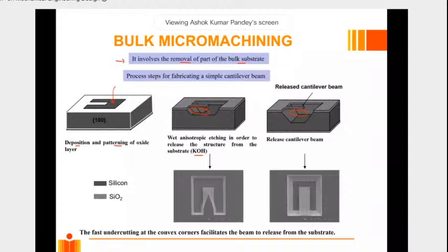So it means the full length is available now, but here you will get only an effective length smaller than the designed one, and that way it will change the resulting frequency. So we have to be careful with these process steps, and the solution that you are going to use for etching these devices.